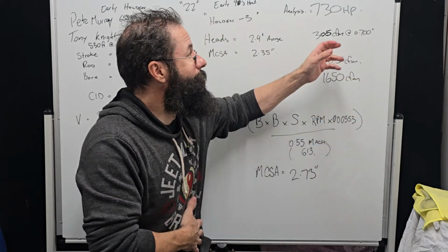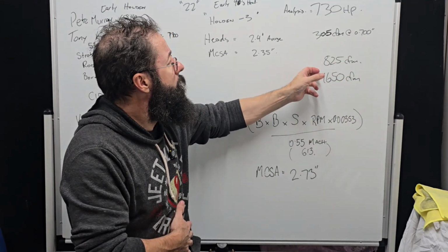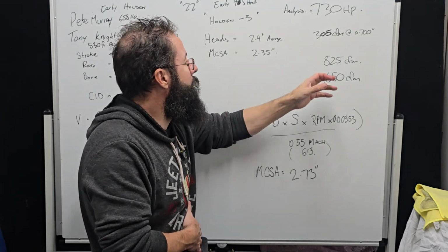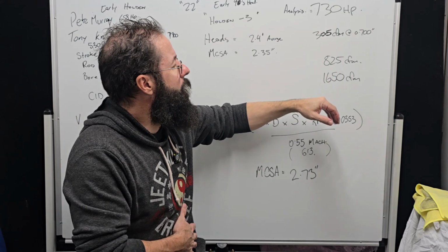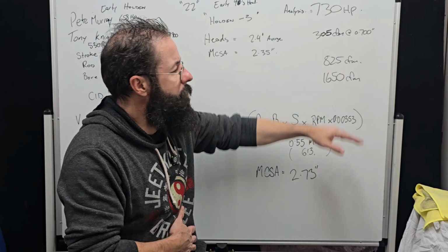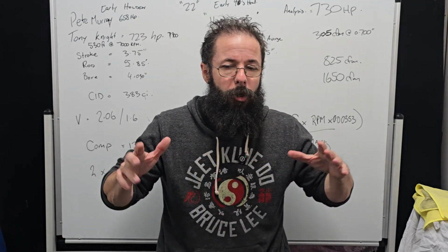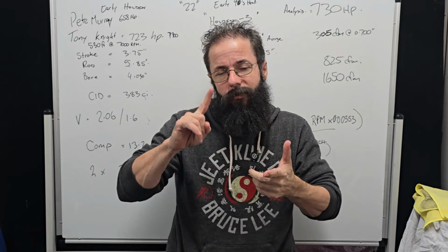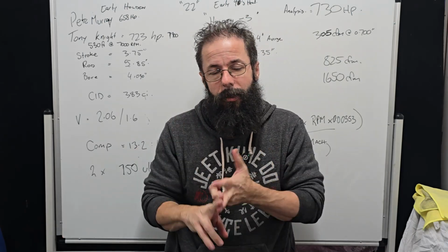But yeah, I come up at around 730 horsepower, but I think Tony was talking about a few things and the way it carried torque and everything. I think 2 825s, that'll get us up to around about that 1650 CFM in total. And with tunnel ram, because we're putting the shot under the carby, we have really good signal. They'll have far better signal than a single plane.